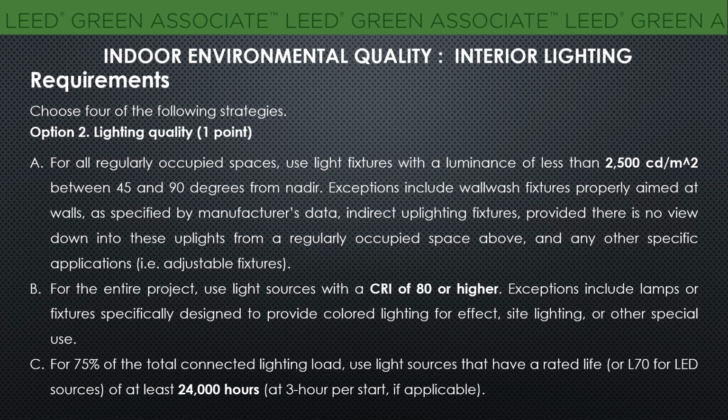Then for the entire project, it's the second point. For the entire project, use light sources with CRI. CRI is color rendering index of 80 or higher. Exceptions include lamps or fixtures specially designed to provide color lighting for effects, site lighting, or other special use.